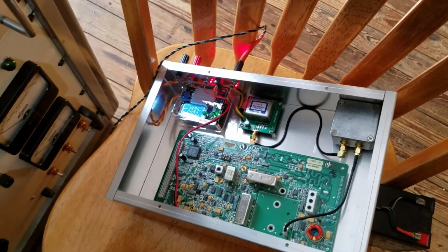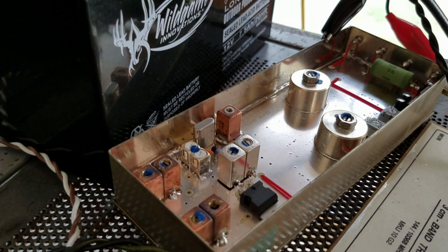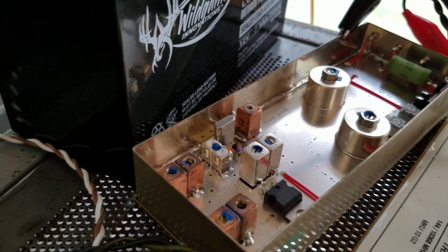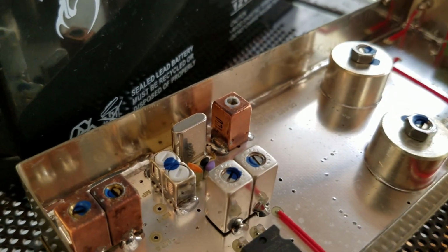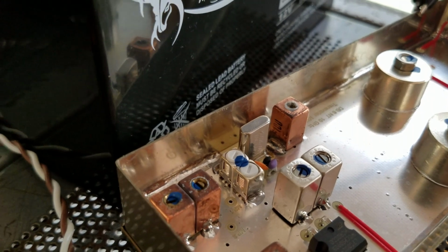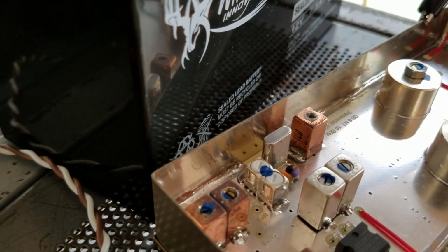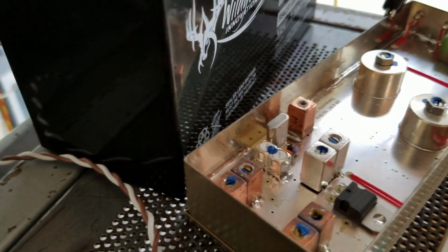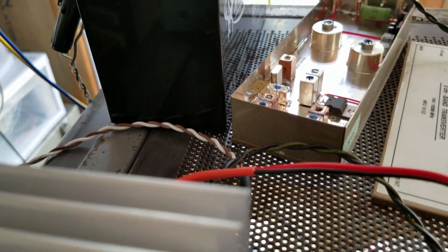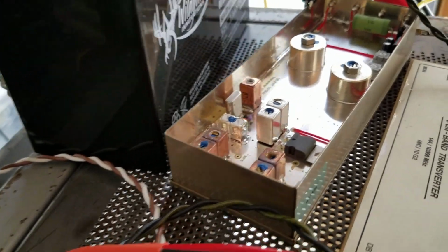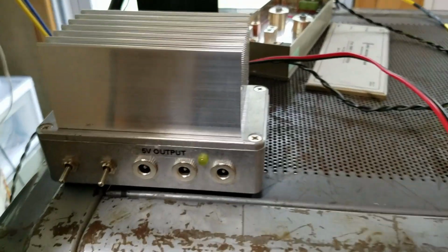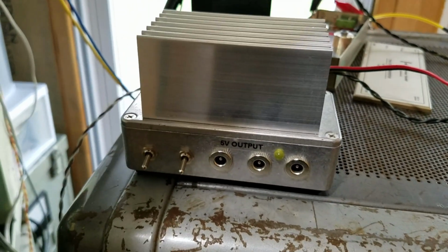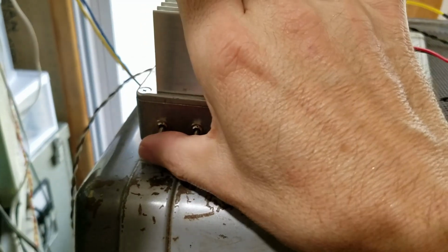I'm expecting that the transverter is not very stable. It's a free-running crystal oscillator, basically. It doesn't have a heater or anything on the crystal there. And this is a 106.5 megahertz crystal oscillator, multiplied times 96 to get to 10 gigs, 10.224 gigs for the LO in this transverter. So even a very small amount of drift at the oscillator frequency will equal a lot of drift at 10 gigs. So I'm going to go ahead and switch these transverters on from a cold start here.